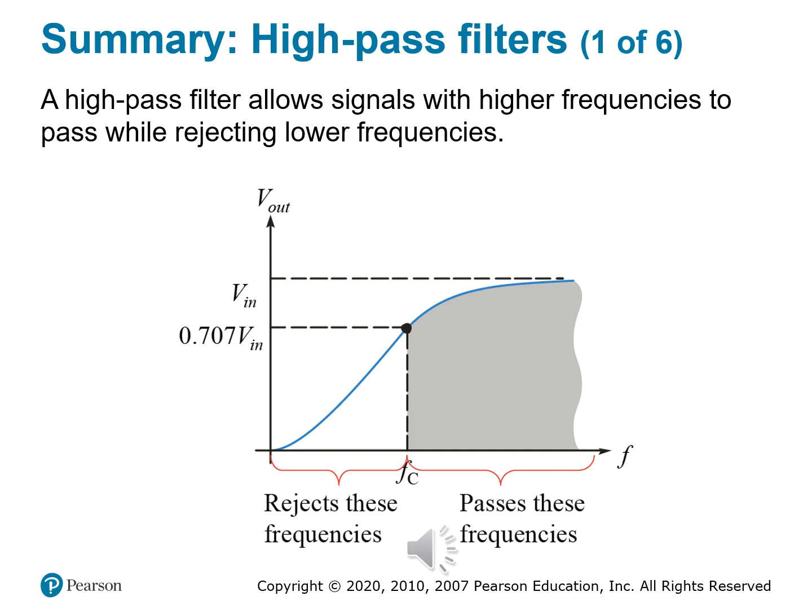So it's important to understand the curve. Let's go ahead and take a look at this graph. The horizontal axis is frequency, denoted by f. The vertical axis is the output voltage, denoted by V sub out. And at first, the frequency is low, right? Output is nearly zero, but as we approach that critical frequency, f sub c, what happens? Boom! The filter starts letting more signal through. By the time we're past f sub c, the filter hits its stride and we're back up to full strength, almost matching the input voltage.